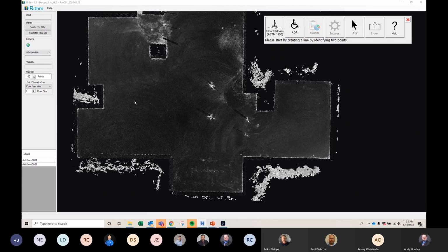But no, if you have a lot of shadows, you limit the amount of locations you can actually pull data from. Does that answer that question? Yeah, because if you run a line over a shadow, is it going to yell at you, or is it just going to jump over it? So according to the rules, it has to pull an elevation point at every 1 foot increment. Okay, so if the shadow's 6 inches wide, not a big deal. But if it's a 2 foot shadow, then it's a problem. Yes, and it will error the line out. Okay, thanks. Let's see if I can actually error a line.